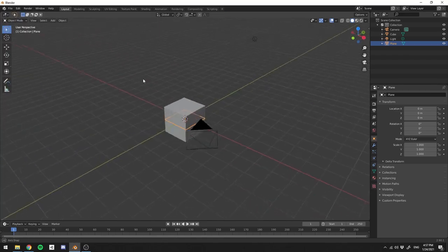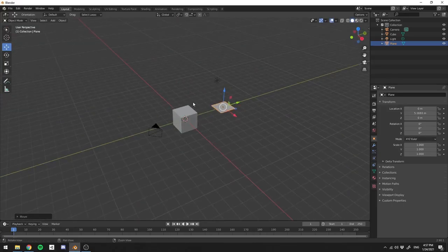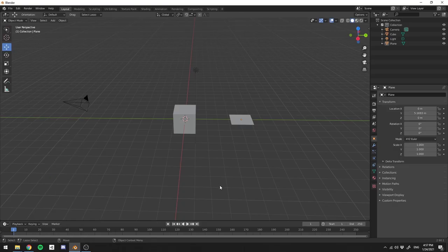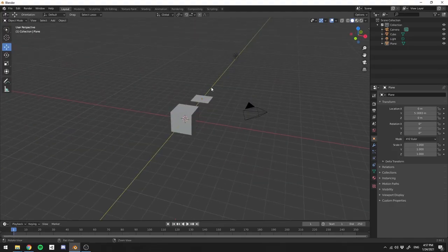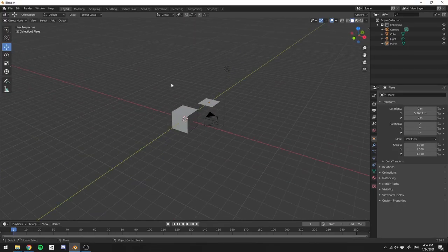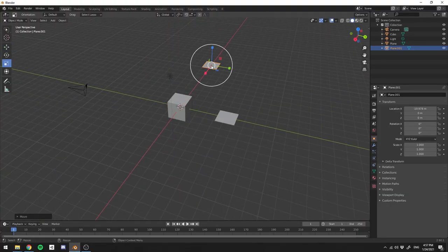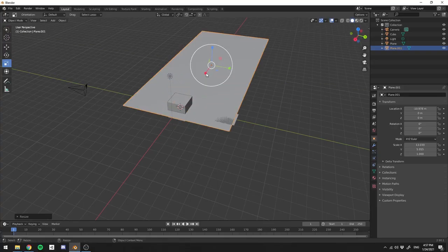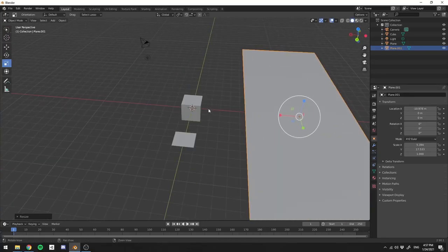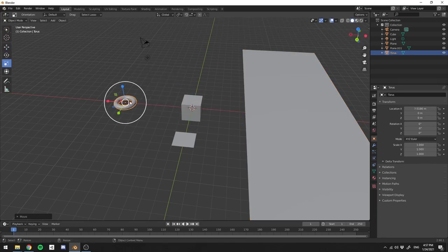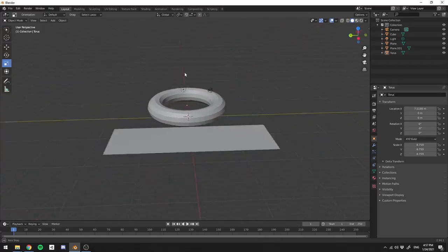Right now I'm working with my industry compatible hotkeys, and if I click Shift A, I get this menu. So you can do pretty much every one of the menus inside the Blender hotkeys and bind them to your industry compatible keys. It's not a problem. This is the method for how you can add them. So right now I have this Shift and A, and I can freely add objects over here, no problem, just like that. Again, Shift A, maybe I can add a torus, I can move it, I can scale it. All right, we have that.